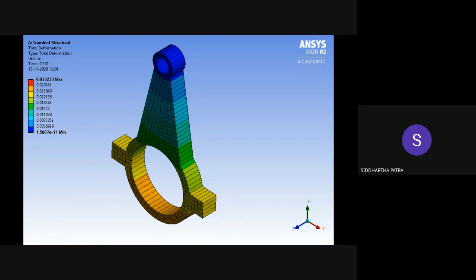So we would oscillate the connecting rod in two configurations. In the next situation, we would make the highest point on the smaller circular hole the pivot point, let the connecting rod oscillate, and note down the time of 10 oscillations.